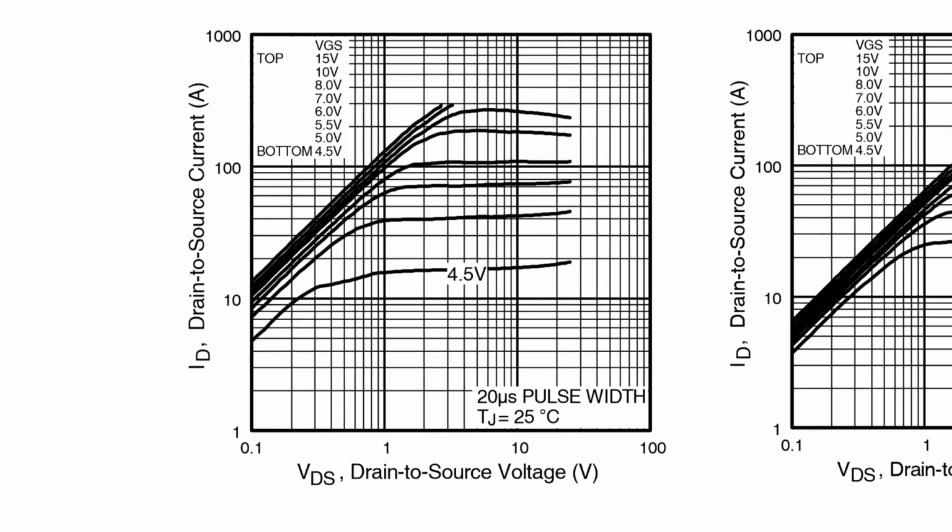One of the things to watch out for as a mechanical engineer is when we plot things like pump curves, motor curves, things of that sort, we typically plot the flow along the horizontal axis and the effort, torque, force, etc. along the vertical. So for example, if this was a piping diagram, you would have volume flow rate along the horizontal and you would have pressure along the vertical. For some reason, electrical circuits tend to reverse those, and so you have your flow along the vertical and your effort variable along the horizontal. So you just have to be aware of that. They're kind of backwards from what we're used to.